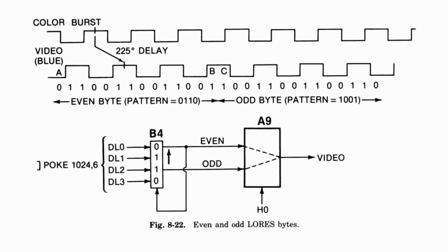There are two gray colors, which arises from feeding the TV every other bit. This produces a waveform at twice the color burst frequency. The TV just gives up trying to guess the phase of this waveform and treats it as having no saturation, in other words, gray. The next group of colors each have three 1s. These are complementary to the dark group. They have the same hues and saturation, but have much higher luminance. Finally, white is color 15, which is all 1s. This doesn't produce a changing waveform, so it's not interpreted as a color, just high luminance. In other words, white. There's one other subtlety in low-res mode.